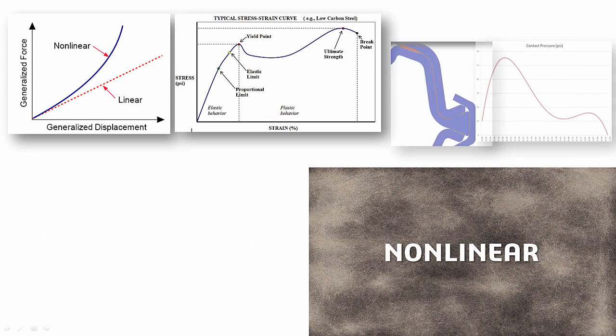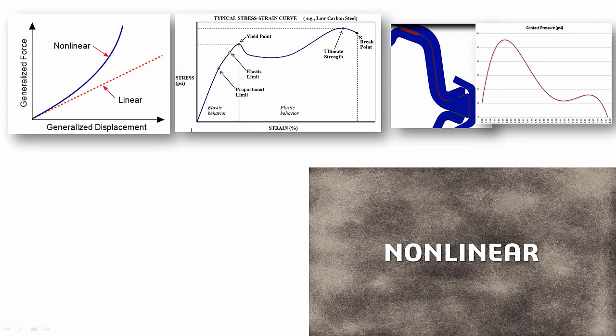Now, jumping into our next flavor is a nonlinear analysis. The difference between the static and the nonlinear is that, well, there are three differences. With the nonlinear analysis, if you remember, with the weaker arm, we had a little warning that said excessive displacements. Now, this excessive displacement essentially causes the stiffness of the component to change, and we need a way by which this change in stiffness and the change in the shape of the component is updated within the software when it calculates what the external force is actually doing to it. We call this geometric nonlinearity.